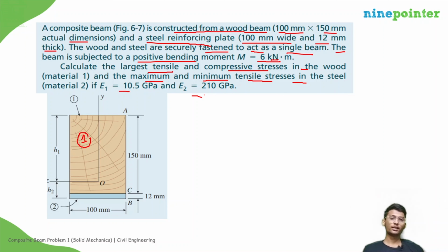See, here the bending moment is positive, means in our sign conventions anti-clockwise moment is positive. Okay, so anti-clockwise moment is positive means anti-clockwise moment is like this, right? So it is like this. Okay, this is positive bending moment which causes the positive curvature. The bending moment which causes the positive curvature is positive bending moment. So this is the positive curvature, right? So in positive curvature, the upper portion will be under compression and the lower portion will be under tension.